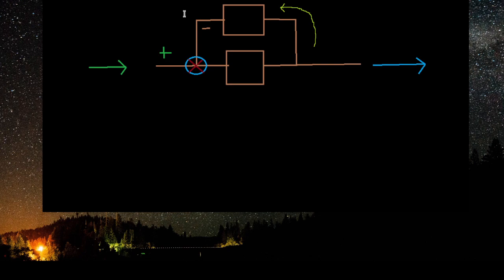Frequency response analysis. Frequency response plots. So this would be if we were to use a sweep generator or not. There's a ripple effect on the end of a filter. Phase Bode plot for G of S. Oh, this is another thing too. When they talk about dB per octave, the higher the dB per octave, the sharper the curve is on the other side of these filters. And it does talk about phase change in the filtering circuits.